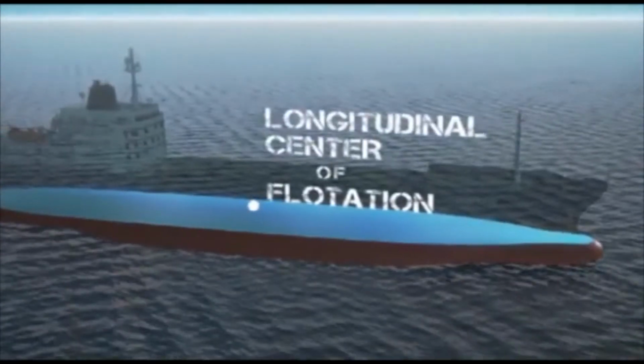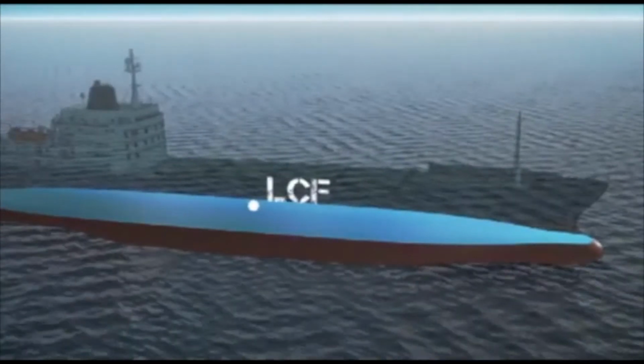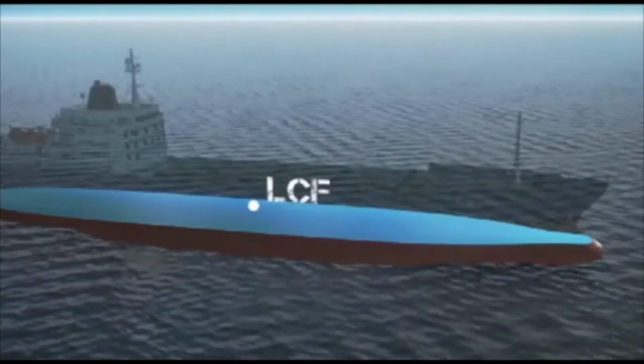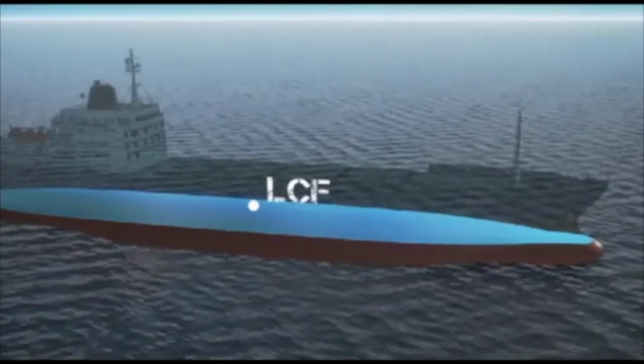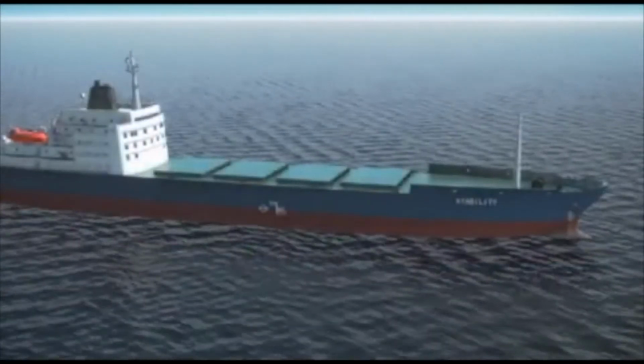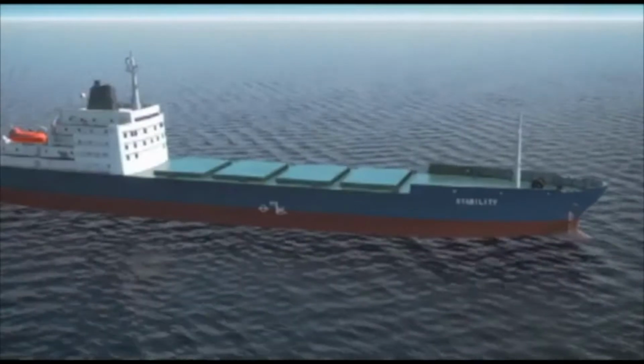Longitudinal center of flotation, or LCF, is the geometric center of the waterplane area. The LCF is the point about which the vessel trims. Note that the LCF is not necessarily located at midships. Its location is determined by the shape of the waterplane area and the trim of the vessel.